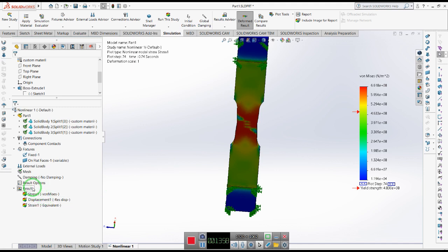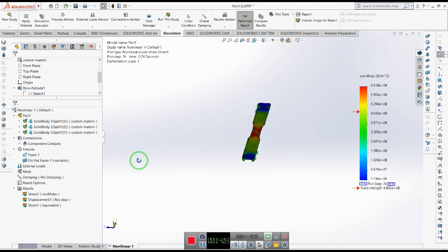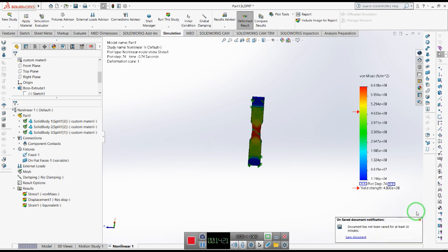I determined the 13 millimeter axial displacement, and after 74% of the running progress of result, an error appeared in my window, and the interpretation of that error was you couldn't determine the axial displacement more than the maximum strain.